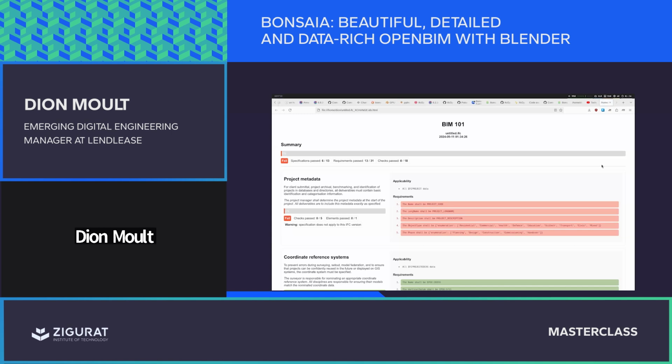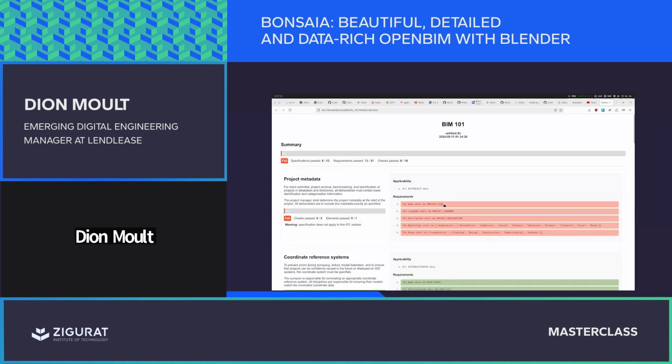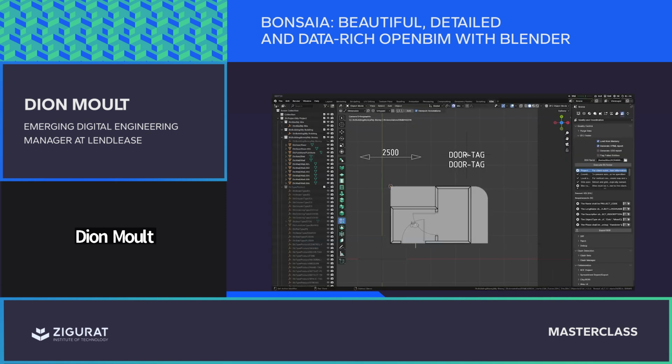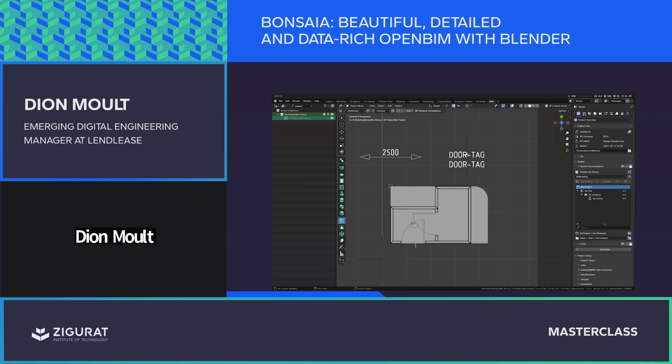Obviously, I am not passing my IDS audit. It has requirements such as the project name needs to be the project code, and it's telling me that it's currently named my project. So let's go and fix that. We'll select project code, jump over to the project object, and change the project code.